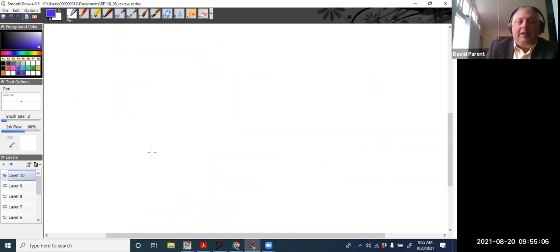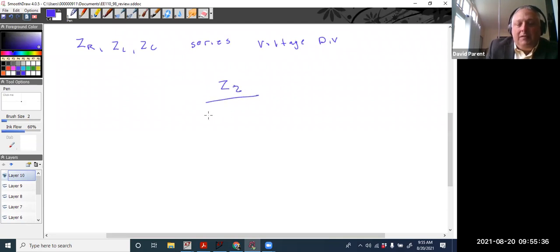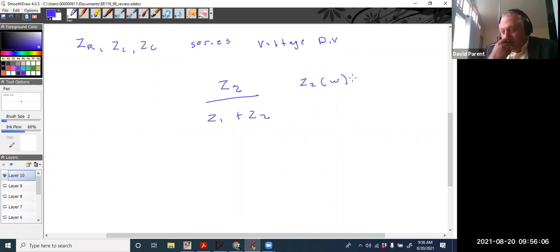All right. So really, to sum up, we've used ZR, ZL, and ZC, and we've used our series thing, which then came to voltage division, which gave us some Z1 and Z2. It's dependent on frequency. Capacitances, it goes down with frequency. Inductances, it goes up. And just by using that and letting omega go to 0 or infinity, we're able to figure out what this filter is going to do. And so you're already designing a filter.